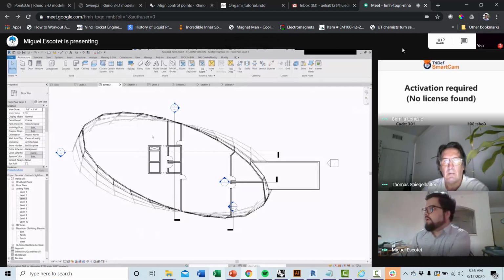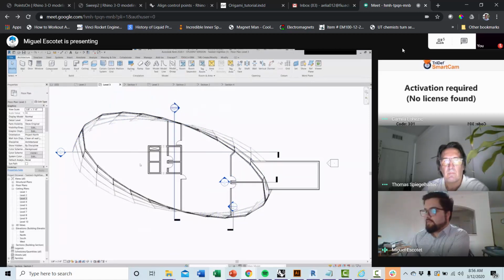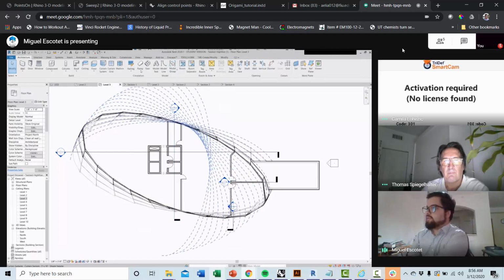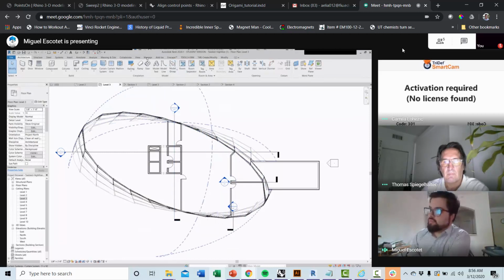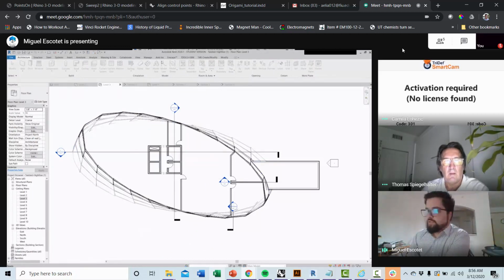First of all, one of the best things to start doing is room assigning and space assigning by the tool rule. Even if you are not going to use specifically rooms, you may want to start assigning the rooms and then assigning the spaces to those rooms.